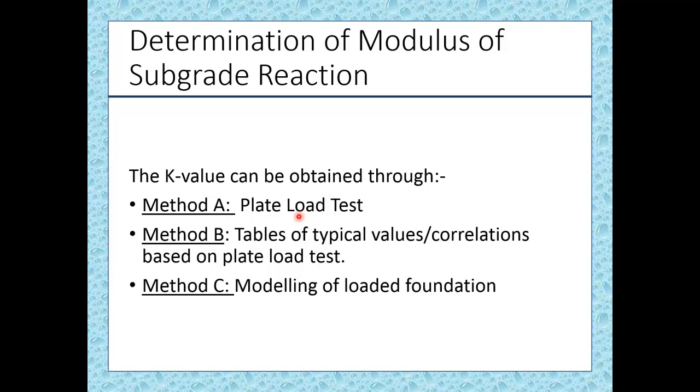This is actually inappropriate for lateral design because it only applies to areas of 1 by 1 feet scale. Method B takes the same values and uses some correlations based on the plate load test. This is a very crude method. The most appropriate is method C, where you model the loaded foundation using finite elements, and we shall be using method C.